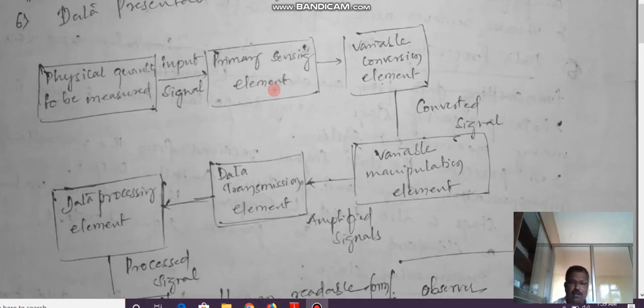So here in this sensing element we are using strain. The load on the load cell is converted into strain, and the strain is sensed by the strain gauge. In this form it can only be read in the electrical form. Electrical forms are nothing but resistance, capacitance. So the strain should be converted into the electrical form. How can it be converted? Here we are using two strain gauges, that is, two sensors.